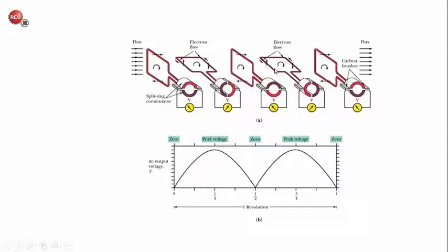And so the current comes out of the page, through the left brush, and from left to right through the voltmeter. That left to right direction of the electrons is the same whether the red commutator was on the right brush or the left. And that's the purpose of the commutator. It keeps the electrons flowing in the same direction through the circuit, always through the voltmeter from left to right. And so the voltage induced across the voltmeter always has the same polarity, a positive polarity.